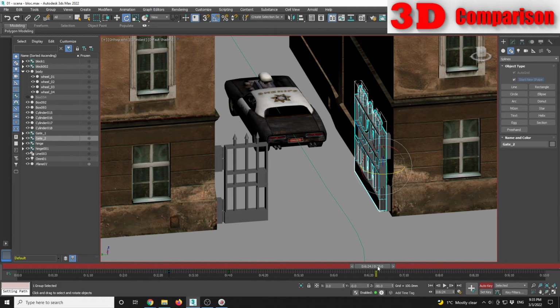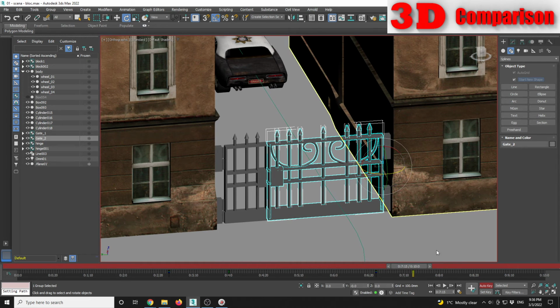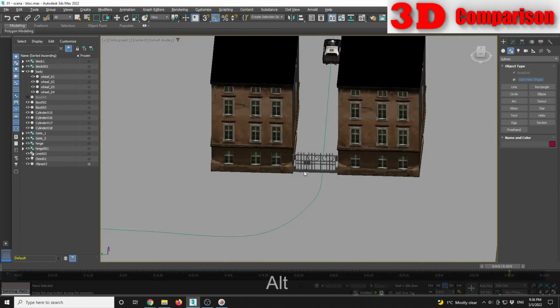We see the filters for rotation. You can also filter them over here, but by default it will be position, it will be red, rotation the green one, and scale over here. But in our case, only rotation is important. You can have them refined. So somewhere along this, maybe 7 minutes 15 frames, I'm gonna have the door close back to 90. And we can now scrub within the animation, and we will see that it works as intended.